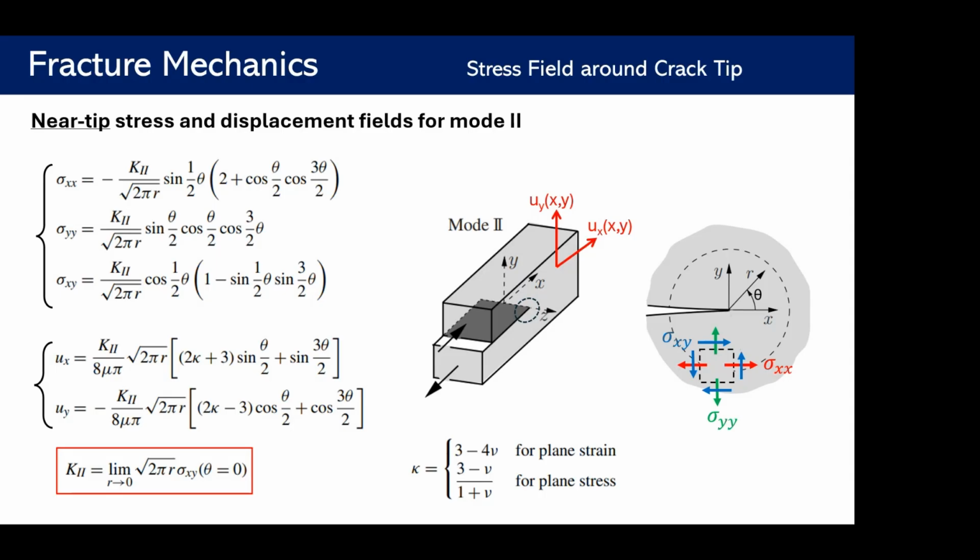So far we have just discussed the functional form, but the most important parameter for us is finding the K, or stress intensity factor, and finding the K, as I said, is not an easy task. There are different methods for finding K. I just want to explain one of those, maybe analytical solutions that can be applied just to specific problems with very simplified loading cases and geometry.